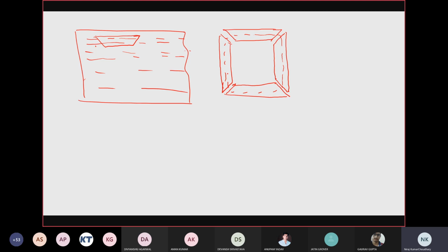So in this condition you will see that the useful flux of the transformer will be totally aligned with the direction of grains. Actually the grains will be totally oriented in the direction of magnetic flux. So the least amount of magnetizing current will be required.